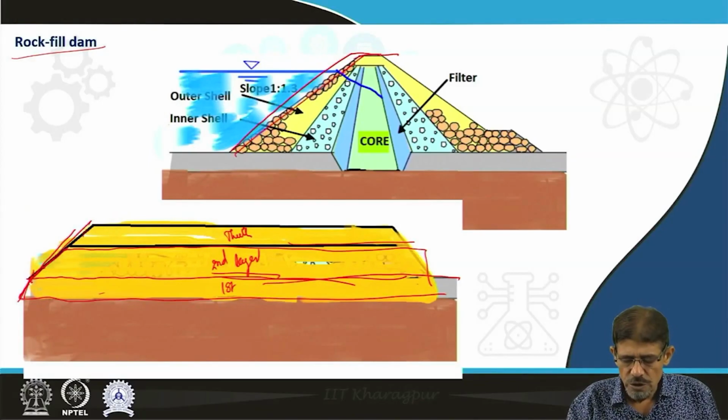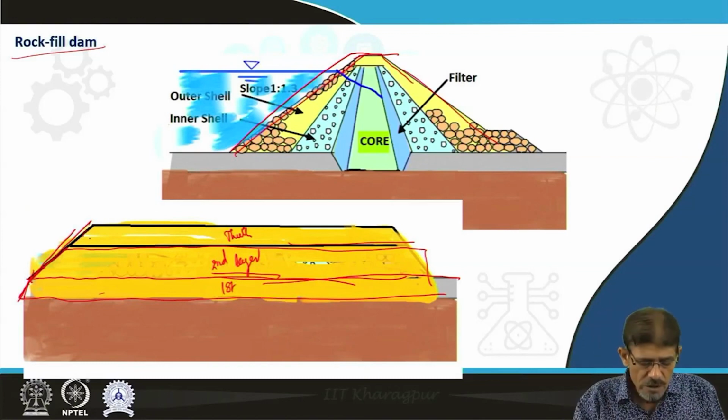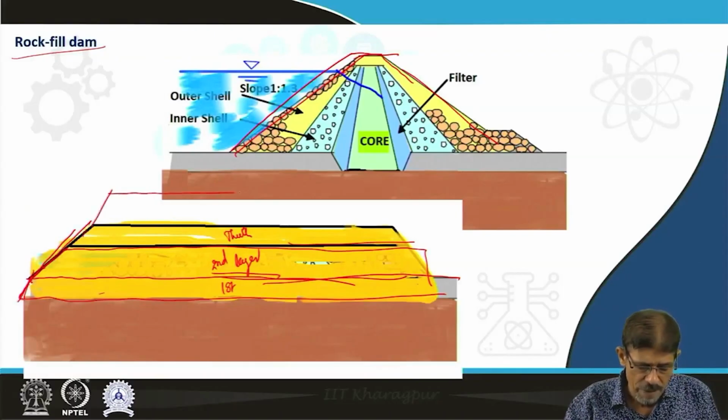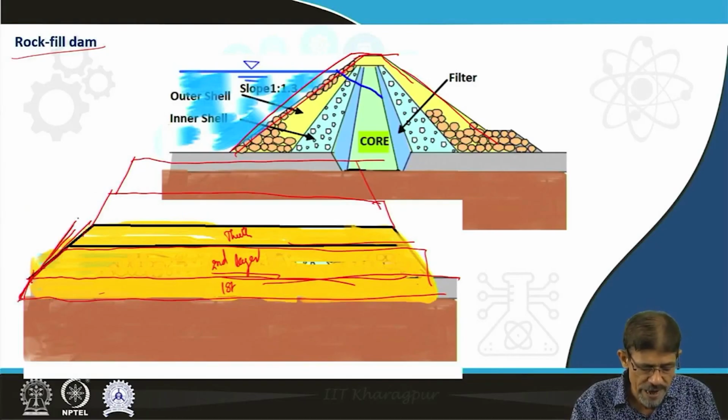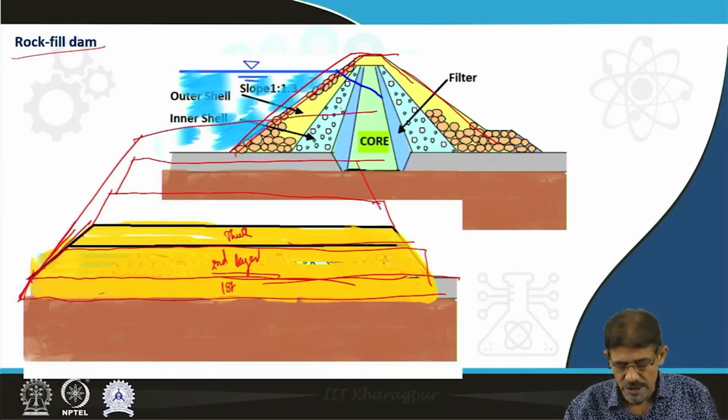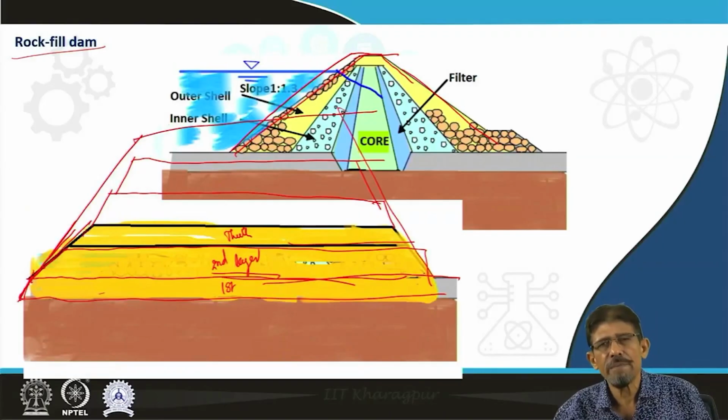Although this presents some different aspect, it is a rockfill dam. In this way we construct this type of structure. The placing of layers one by one to create a trapezoidal section is recognized as an embankment dam.